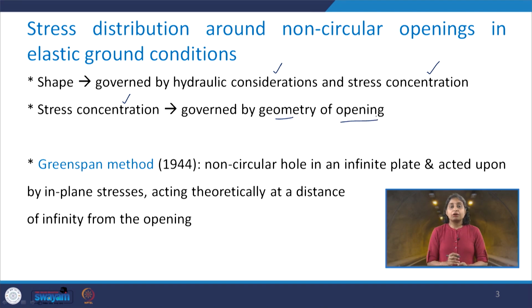Non-circular openings analysis in elastic ground conditions was given by Greenspan in 1944, where he considered a non-circular hole in an infinite plate which is acted upon by in-plane stresses, and these were acting theoretically at a distance of infinity from the opening. It is exactly the same as we did in case of the circular tunnels, where we considered that the applied stresses are acting at a large distance, or maybe at an infinite distance for all practical purposes.